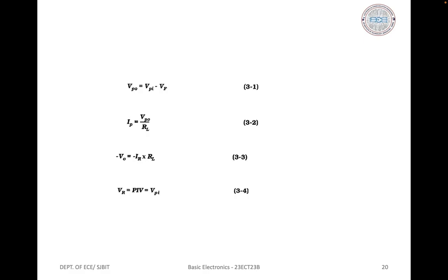However, most rectifier circuits use a reservoir capacitor at the output terminals to smooth the rectified voltage wave into direct voltage. It becomes very important to note that the presence of the capacitor changes the output waveform and that it substantially affects the load current and voltage and the diode current and voltage.